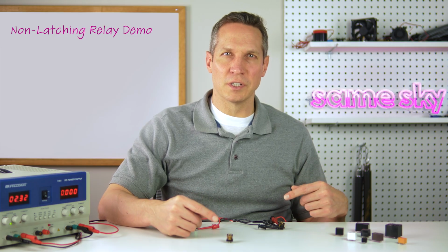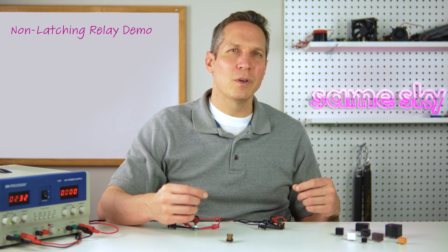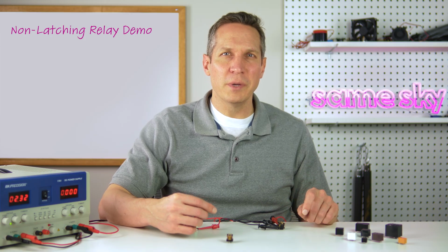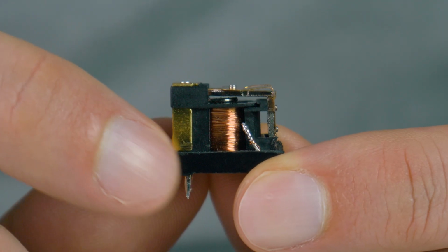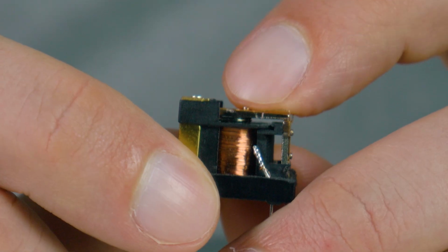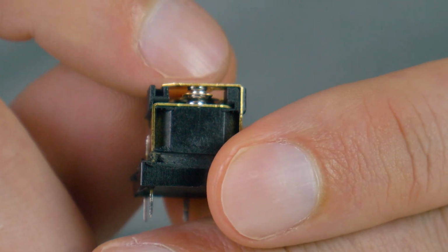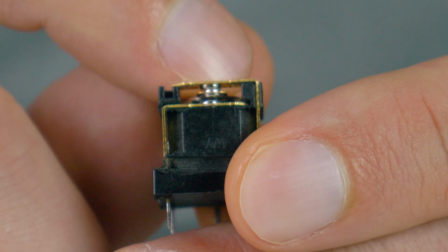I was able to remove their covers so you can see how this electromechanical relay works. While the exact configuration of a relay changes from model to model, all the main components are there. You can see the coil here, the spring on top that returns it to its normal position, and then the contacts here on the other side, where actuating the relay causes the moving contact to switch between the normally closed position and the normally open position.